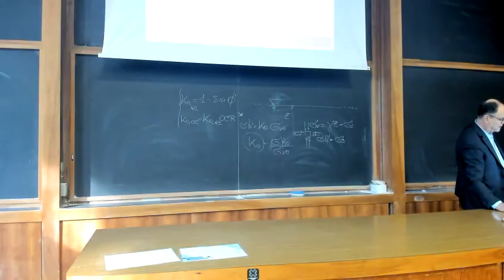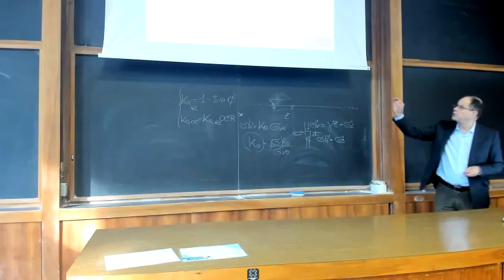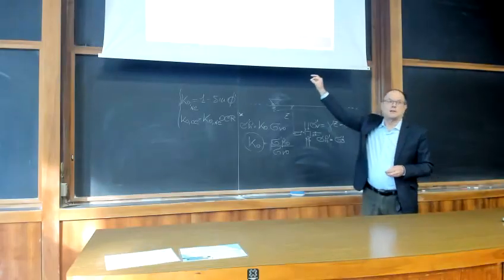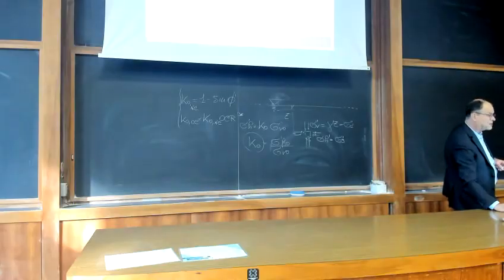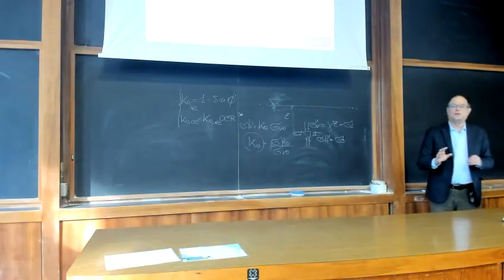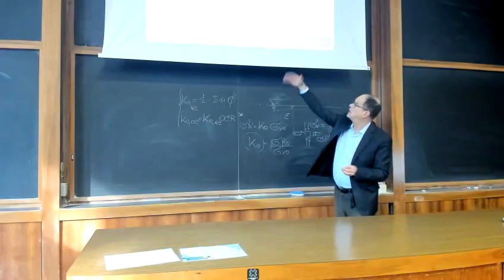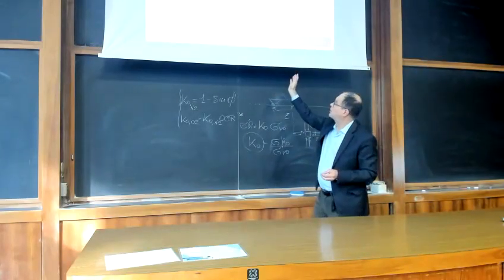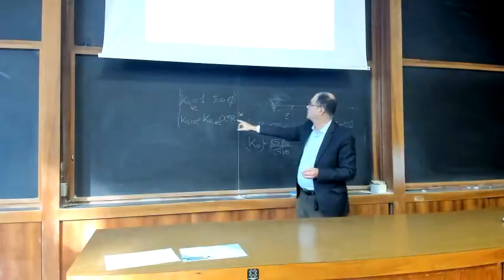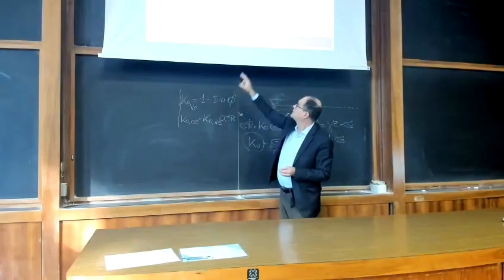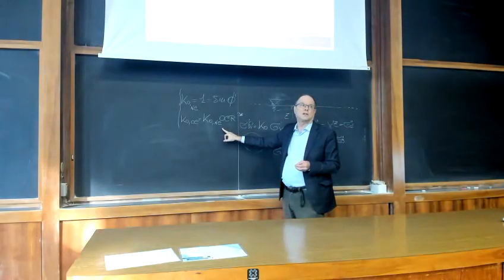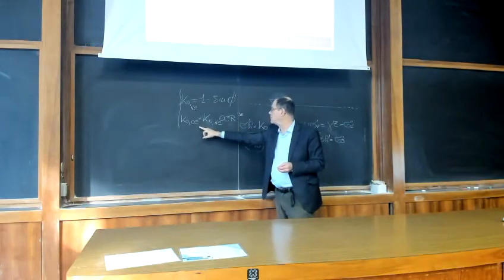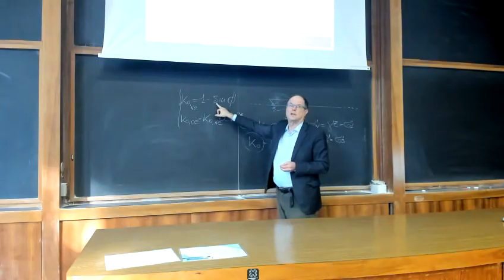We have the vertical stress, effective vertical stress, which is a principal stress. So the point lies on the sigma axis. You might have a horizontal stress in initial conditions, which is not statically determined. So it can be any point. It can be on the left-hand side, if K0 is less than 1. It can be on the other side, if K0 becomes greater than 1. Is it possible to have a K0 greater than 1? Yes, because this is certainly less than 1.